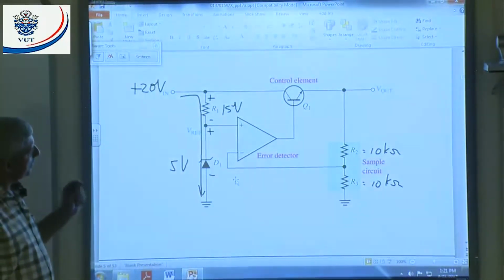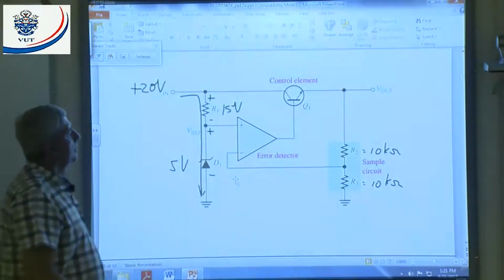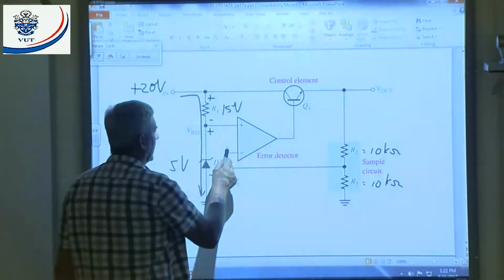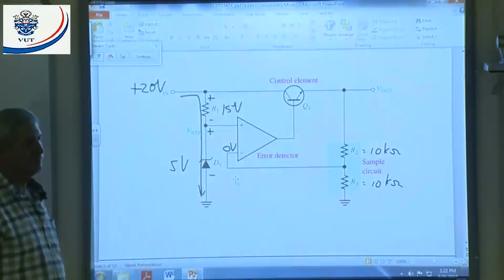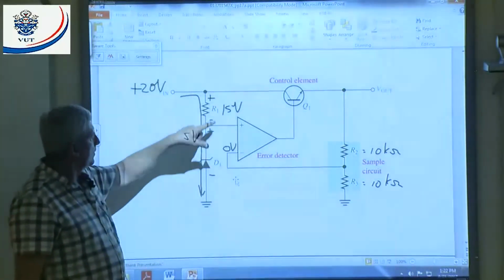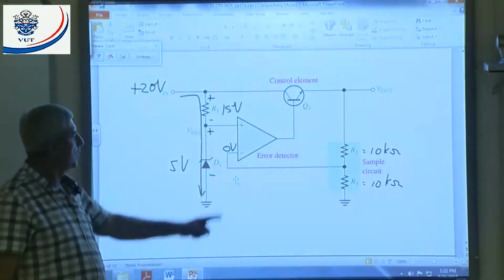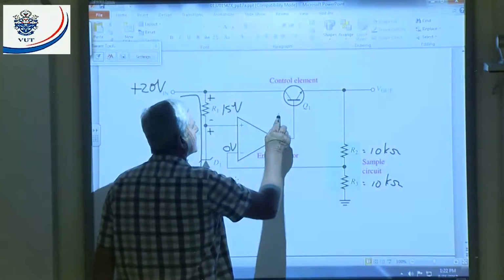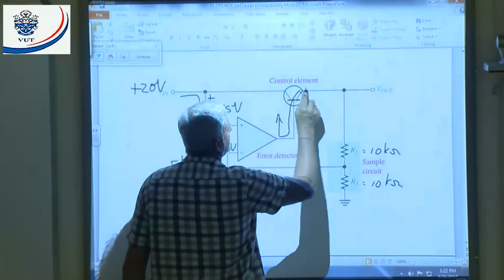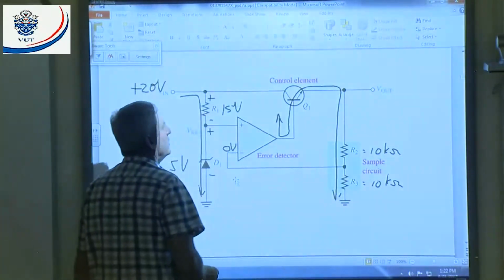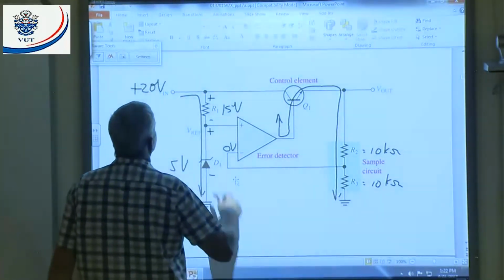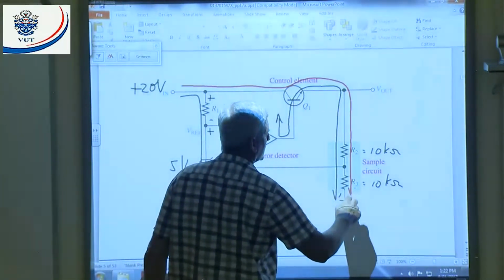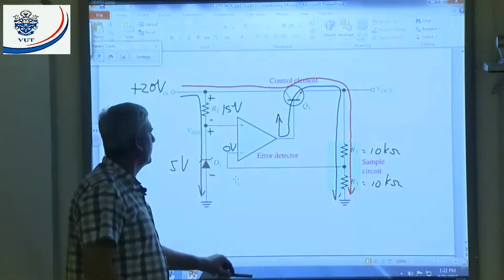Now, what will actually happen? When we switch on the power, this transistor, this op-amp, there will be a positive voltage here. What will be there? At that instant, 0, all right. What is 0 with respect to positive voltage? Negative. Where will the output of the op-amp go? Will it go positive or negative? It will go positive. It will increase, all right. Doing what? Creating a base emitter current that's going to flow, all right. And due to that, I will get a much larger collector emitter current to flow, all right. You agree? That means we switch on the transistor.